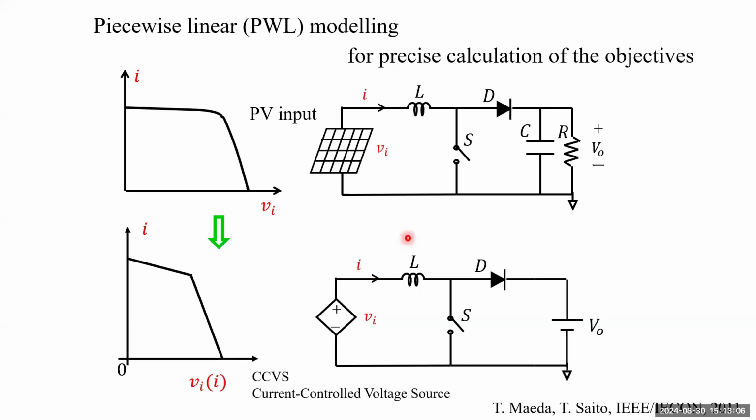It is controlled by the inductor current. And also, if the time constant of the load is much larger than the clock period, this load can be simplified into a constant voltage source. In this simplified system, exact analysis is possible. And the result can give basic information to analyze various realistic systems. This system is very convenient.